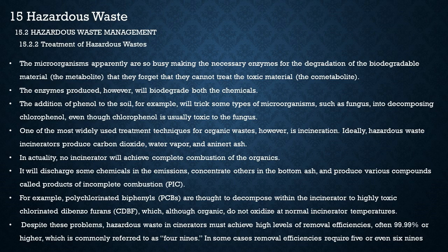In actuality, no incinerator will achieve complete combustion of the organics. It will discharge some chemicals in the emissions, concentrate others in the bottom ash, and produce various compounds called products of incomplete combustion. For example, polychlorinated biphenyls (PCBs) are thought to decompose within the incinerator to highly toxic chlorinated dibenzofuran (CDF), which, although organic, do not oxidize at normal incinerator temperatures.